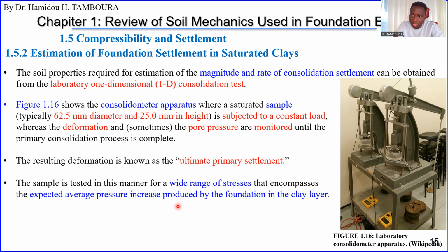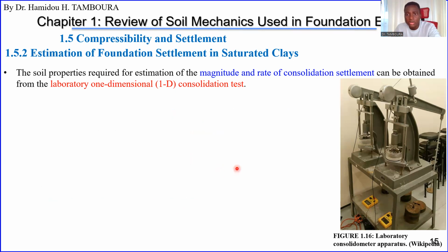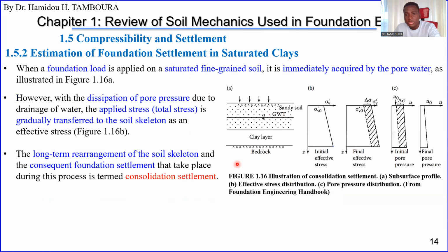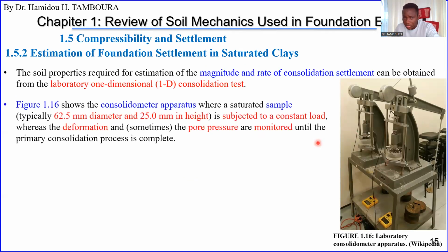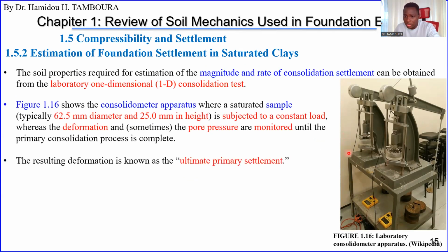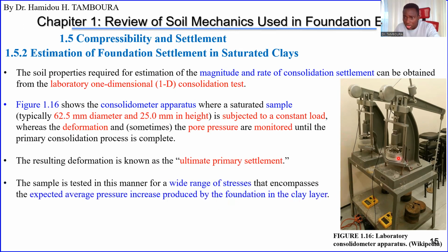The previous slides show a granular soil layer and a clay layer. Let me go back a little bit. What is the amount of stress that this clay layer will receive? According to that average, you will do your 1D consolidation test with this amount of stress.